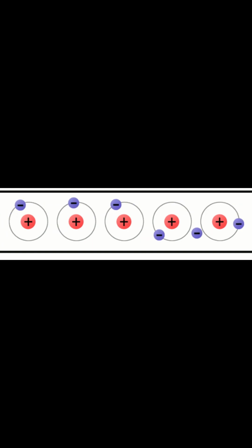The formula shown can be used to compute the speed or wavelength a signal travels through a conductor. Wavelength is the distance that current travels during one cycle of alternating current. L equals 984 V over F. L equals length in feet, V is the velocity factor, F is the frequency in megahertz. The velocity factor is determined by the type of conductor.